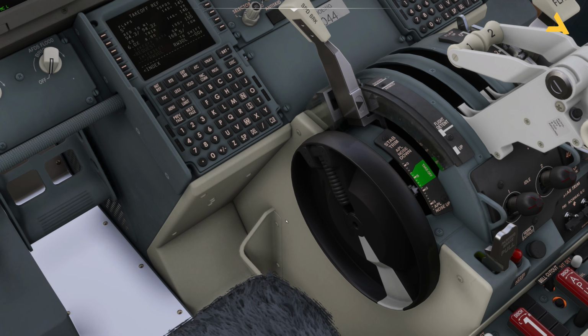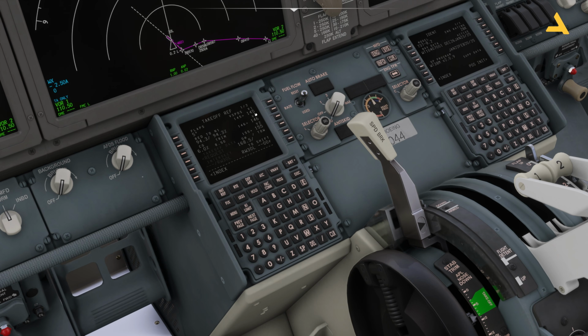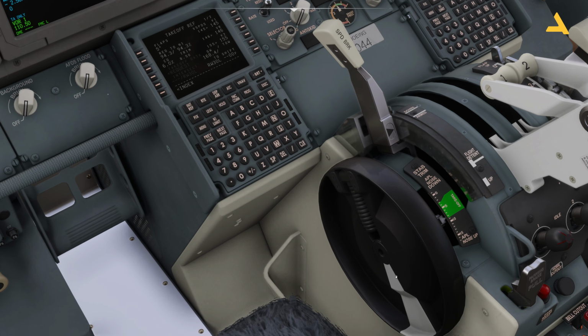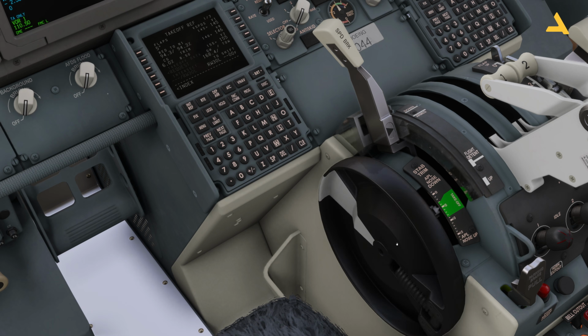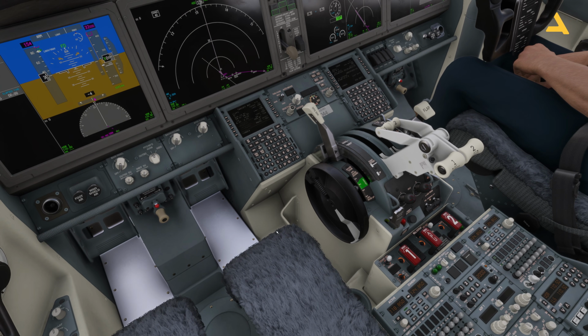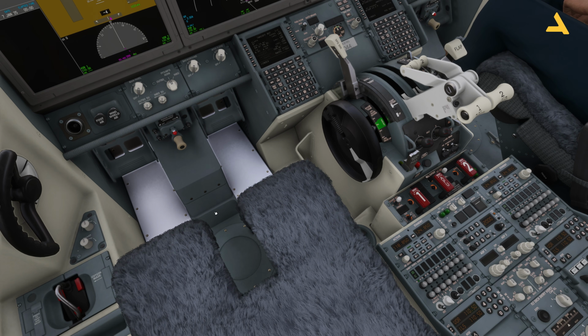But what I've experienced is this, that with these speeds, 145, 146 and 155, and with this flap setting, the plane automatically takes off. You don't even have to use the control for this. So I think maybe these speeds are very high. It should be around about 130 to 135 knots, or maybe this trim setting is high. So maybe you can do some flights, and then you can just keep it somewhere here, 5 or 6. Just try some flight with it, and let's see if you get a good takeoff.